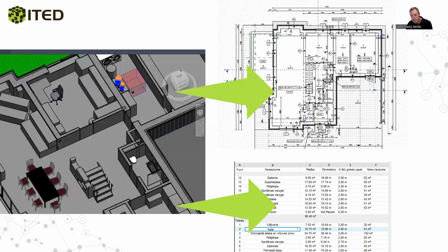And after all that testing and changes in the 3D environment, you can easily extract the same old 2D drawings and quantities directly from the 3D model. But there is a huge difference. The 2D information has a direct link to the 3D model, meaning that if you, let's say, move a wall, the finishes table and also all the drawings will update automatically. That also hugely reduces the amount of errors.